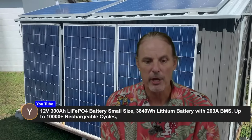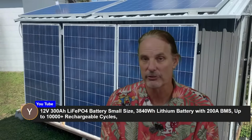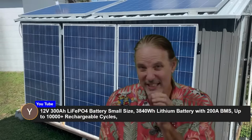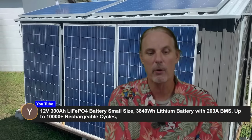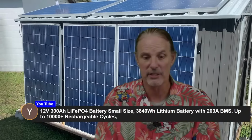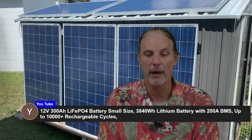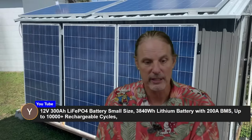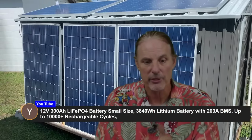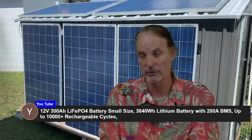So in this case, you have a 300 amp hour battery, but he also specified that it had a 200 amp BMS. And so not always in the case do these match one for one. Usually if you have a 100 amp hour battery, you also have a 100 amp BMS. In this case, Brian from Oklahoma has a 200 amp hour battery. Most likely you have a 100 amp BMS, whereas in the case of YouTube here, he has a 300 amp hour battery with a 200 amp BMS. So the BMS size is what's important here.